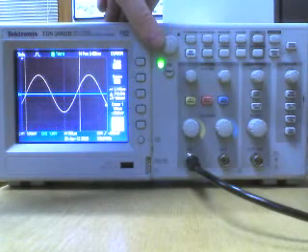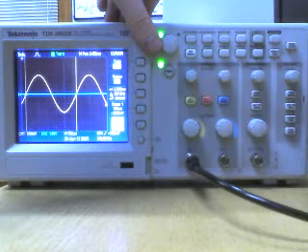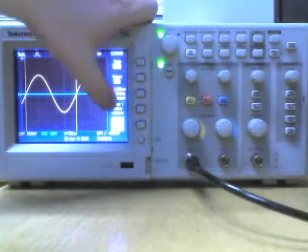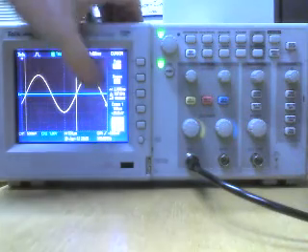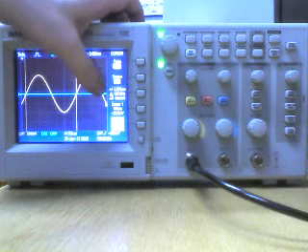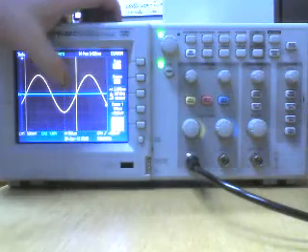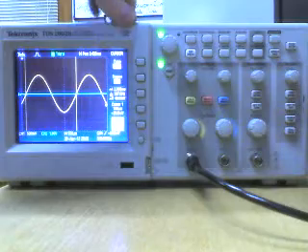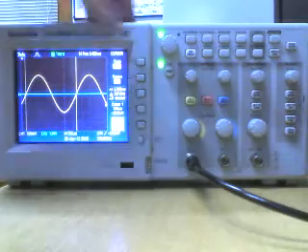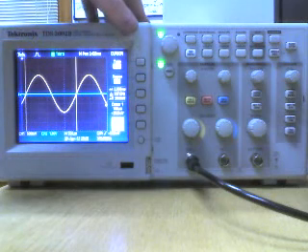To the end of our sine wave over here, the sine wave is at 3.12 milliseconds at the 0 crossing point. The difference between the two is 2.96 milliseconds, very close to our 3 milliseconds when we counted the divisions. But it's actually off by a very, very small amount, points of a millisecond.